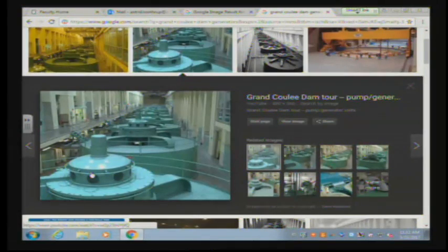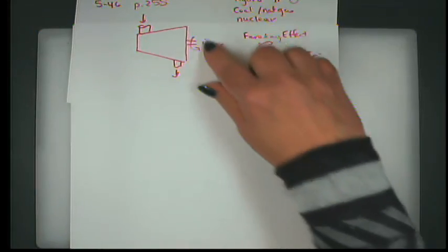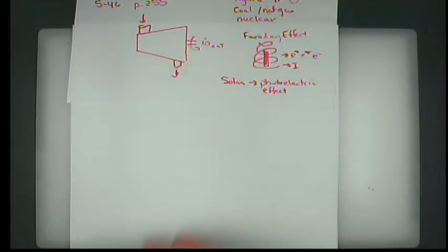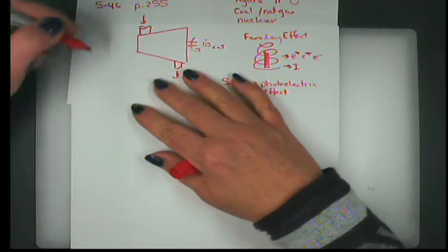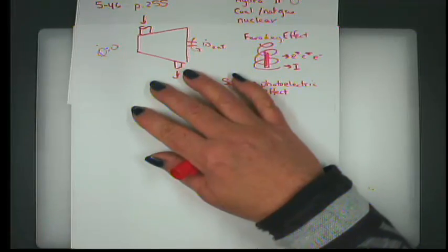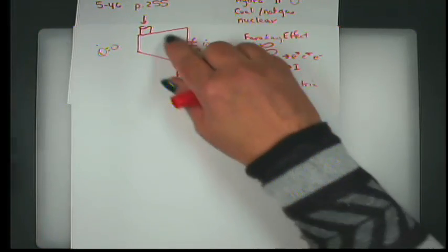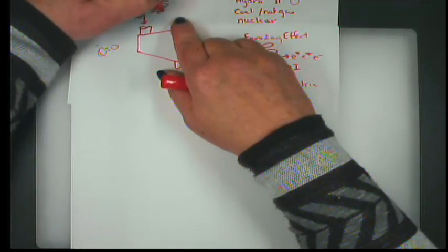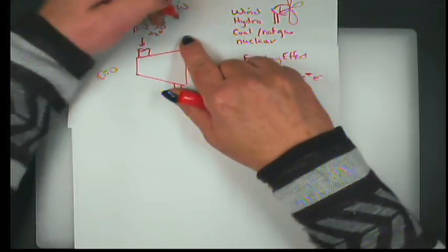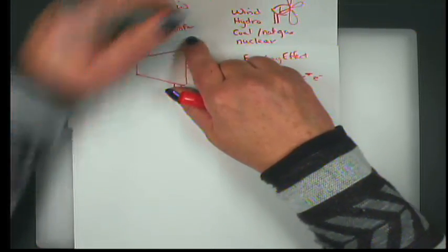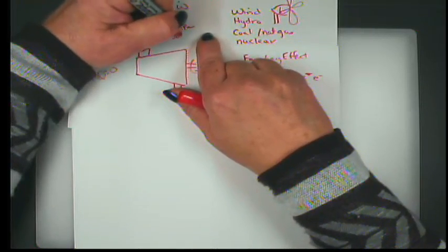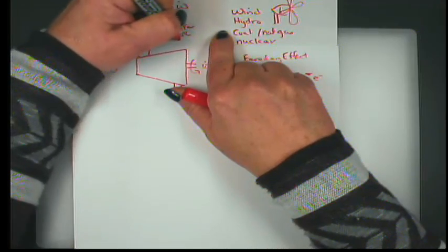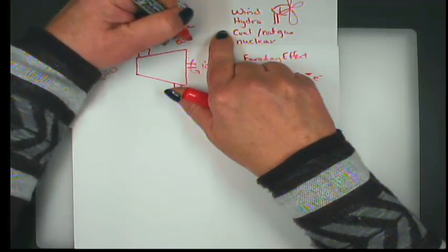So anyway, getting back to our basic example. We have steam flowing through this adiabatic turbine. Adiabatic means that Q dot is equal to 0. The inlet conditions of the steam, we have water, and it's at 4 MPa and 500 degrees centigrade, and it is going through at a velocity of 80 meters per second.